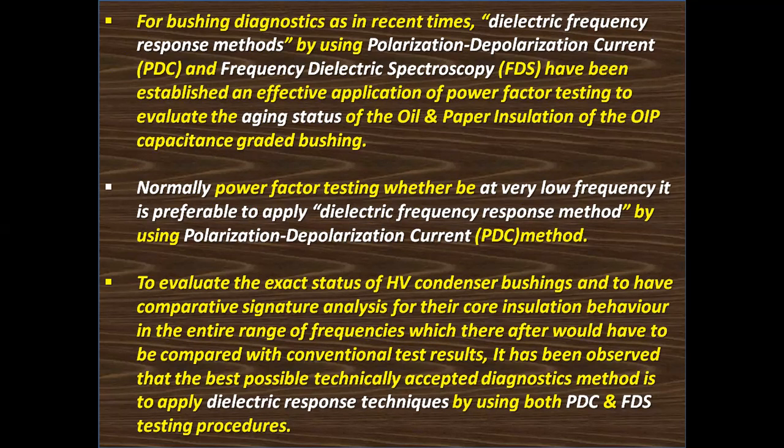Normally, for power factor testing, whether be at very low frequency, it is preferable to apply the dielectric frequency response method by using the polarization, depolarization current method, that is PDC method.